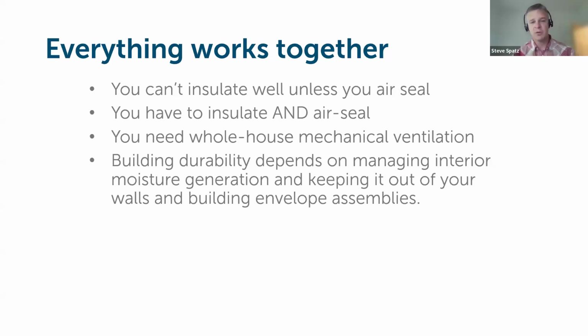You don't want separation between your thermal control layer and your air barrier layer. The vapor control being integrated in that as well. And then, as I said, the building shell is a passive assembly once complete for the duration of that building's life. But then you do need effective whole house mechanical ventilation to keep the potential of loading in check within the building. And so you need both the passive and the active components of moisture management in the building to remain durable over time.